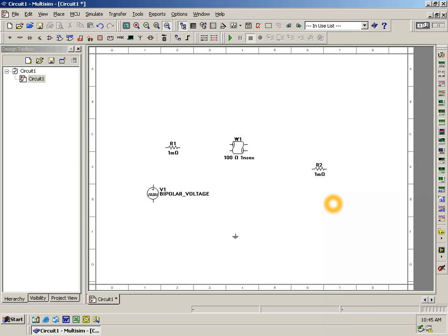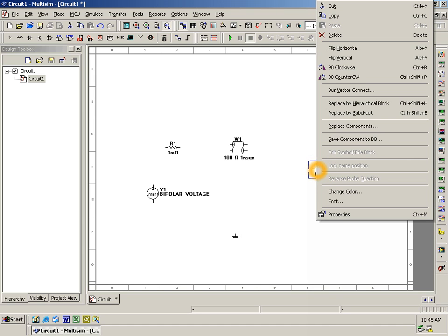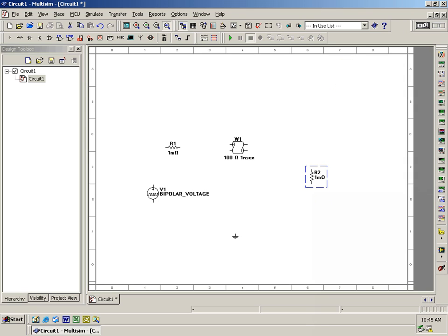And I think that's going to be it. Let's turn this guy around a little bit so it looks a little better. Alright, so now we're going to wire this. Sometimes this wiring can be a bit of a challenge. We're going to take that load resistor and put it to the coax. Now, these numbers are node numbers. We'll use those to select voltages and other things later on.